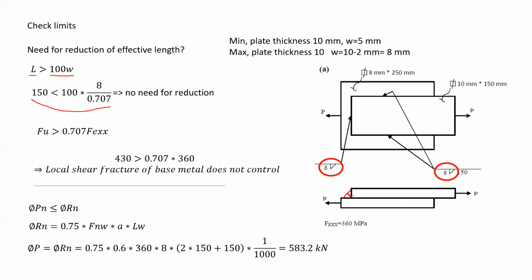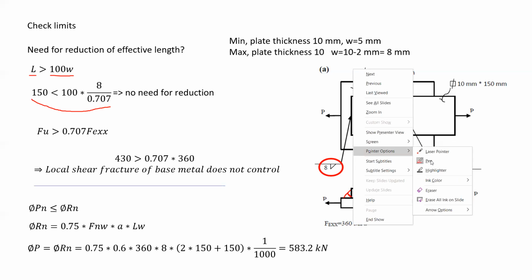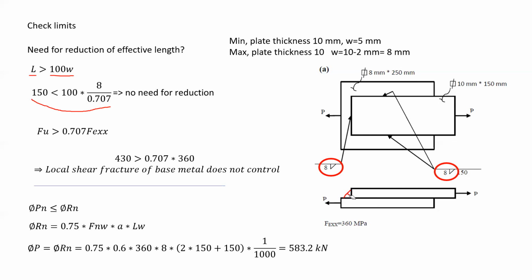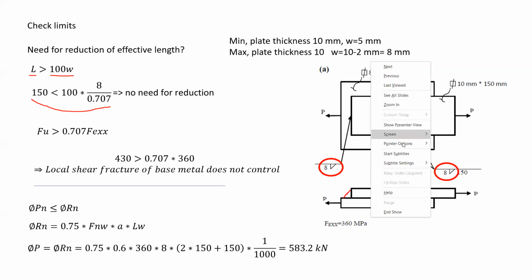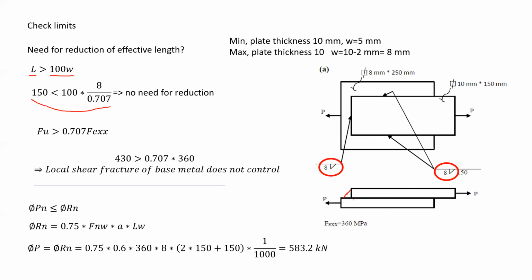And these two pieces will be separated at the throat of the weld. However, there is another way of failure that I would like to explain. Instead of having the failure in the throat of the weld, you might have the failure in the base metal. So the weld might come out taking a piece from the base metal, and this part would completely go out, as I'm showing. If it goes out, of course, the two pieces are separate from each other.